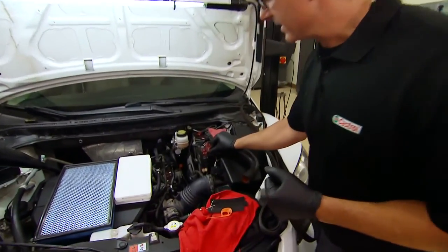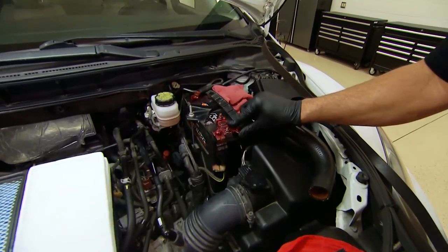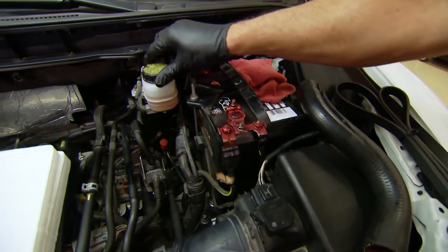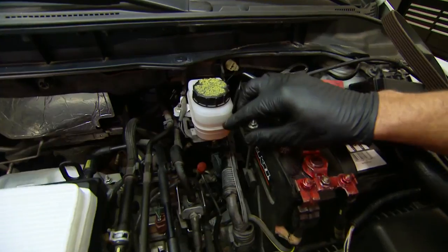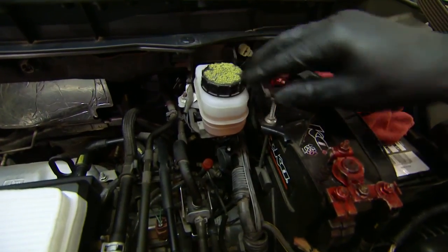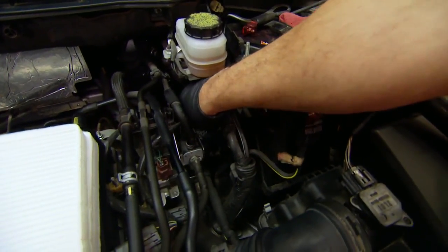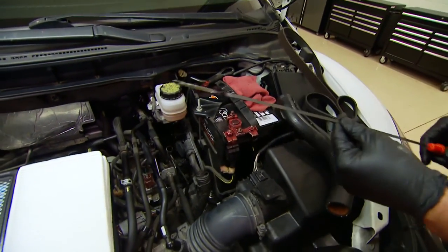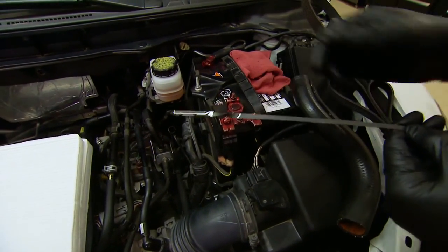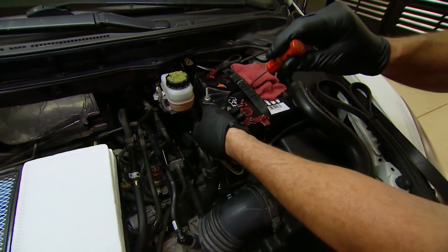This vehicle here, you can take a look at the battery right here, make sure the connections are in good shape. Just work your way over to the brake fluid. Look at the level, make sure the cap's intact. Down here you have the transmission fluid. Now, every vehicle is going to be a little different. You can pull out the transmission fluid, either look at the service manual or read the stick on how to check your vehicle when you're working on it.